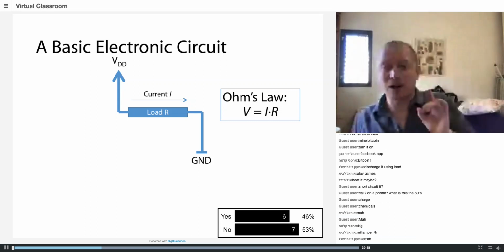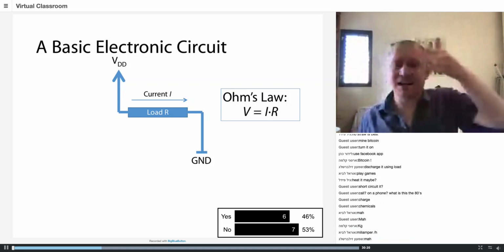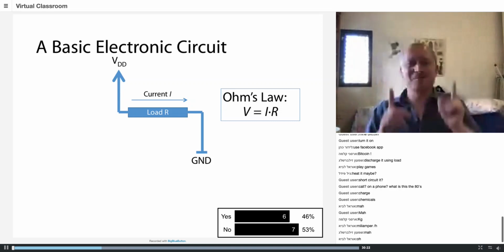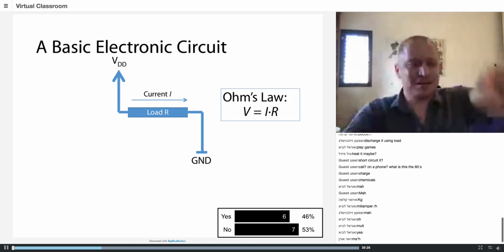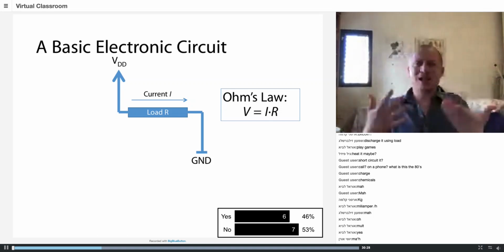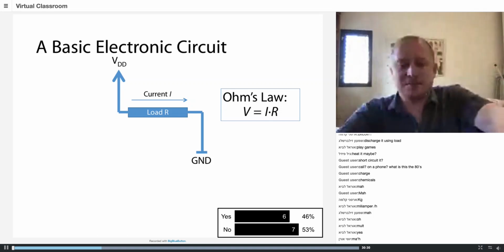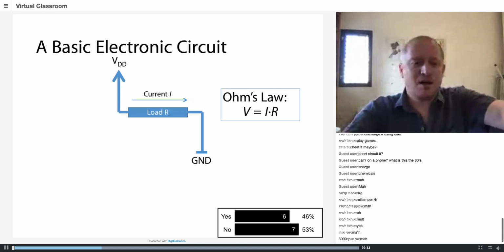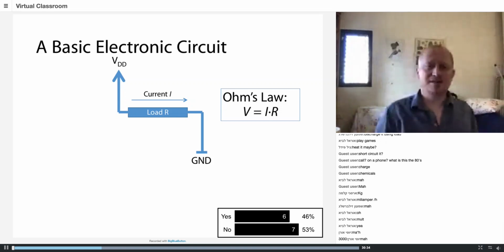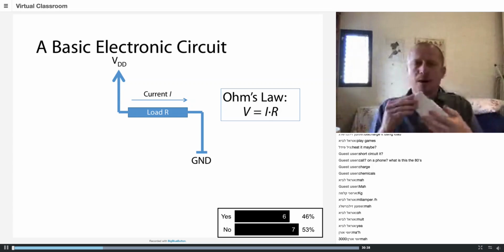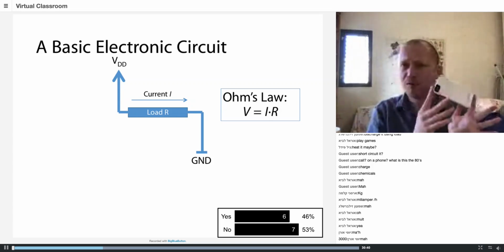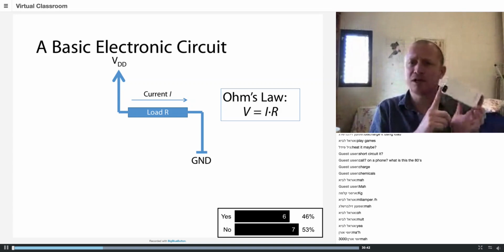I have to correct you: it's not milliampere divided by hour, it's milliampere multiplied by hour. So it's milliampere times hour. So milliampere hour means that if I have a 3,000 milliampere hour battery, and I'm consuming 1 ampere of current, how long will my battery last until it runs out?